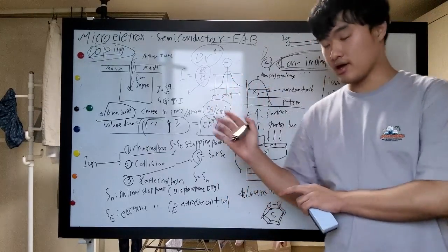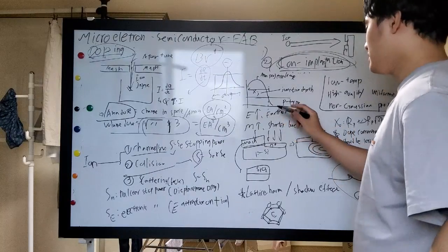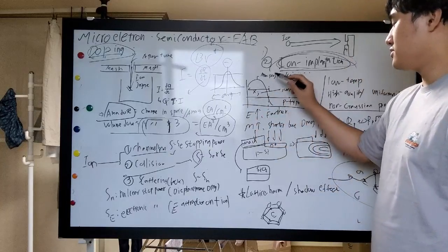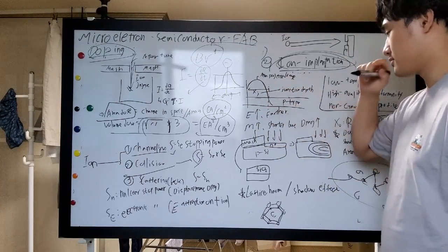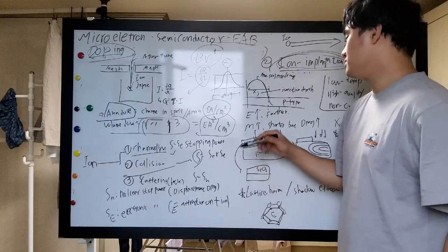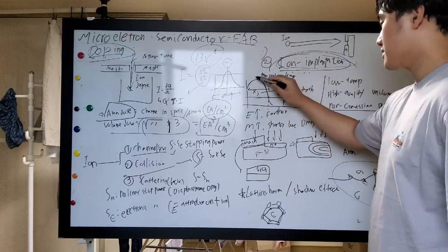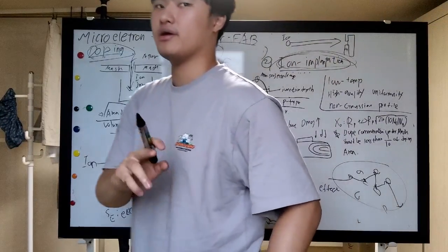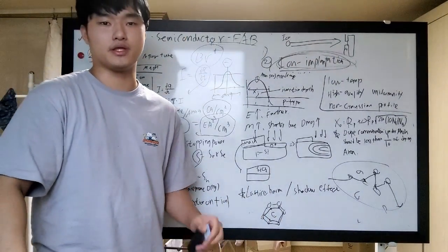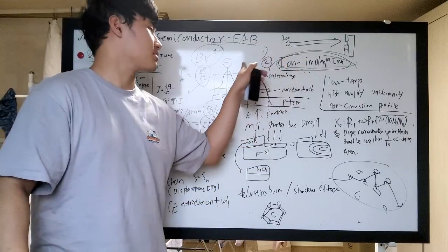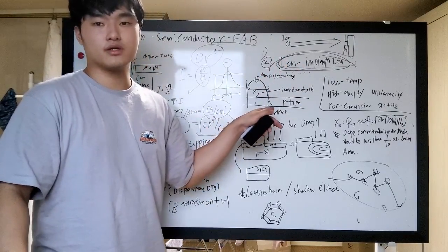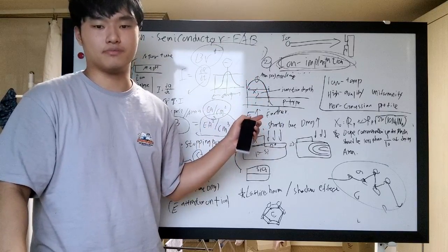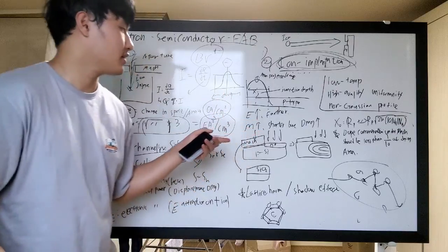I know what this means. If we are doping a p-type silicon here with an n-type dopant, then the height with the highest value means that at this distance, the most ions will be collected and make a doped area.